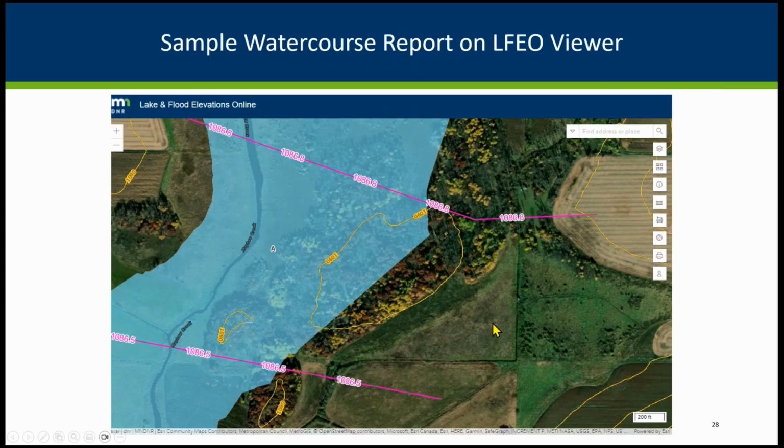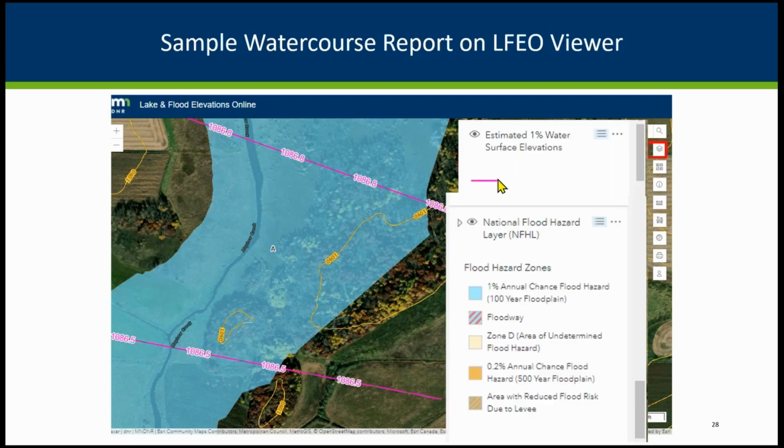So here's an example where we've got an unmodernized map, and here's another example showing the same things, but on one of the newer DFIRM counties. And unfortunately, it must be one of the DFIRM counties. Yeah, it is. It looks like it's in Benton County. And it was done before we had as much LiDAR backing, and they didn't delineate along the contours based on LiDAR, you can see here. But we did have some supporting models and have the cross sections, these can be used as best available data. And if you're between a site, you can always take that upstream elevation, and that's a good estimate for your BFE. Okay, there we go, showing the symbology here.